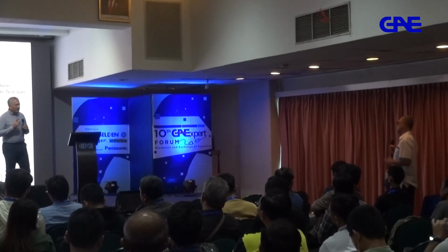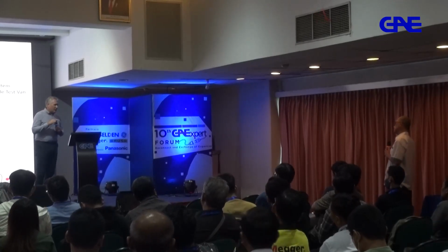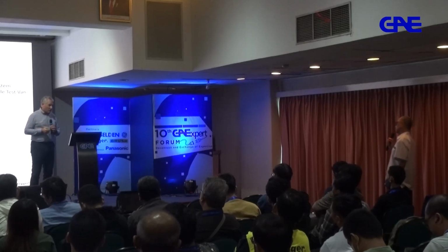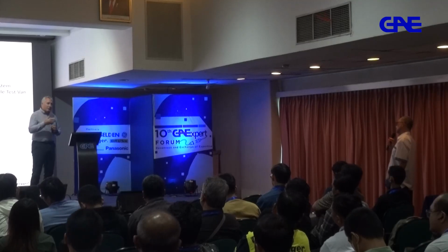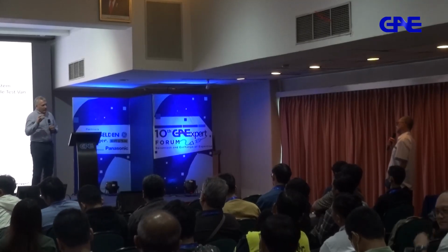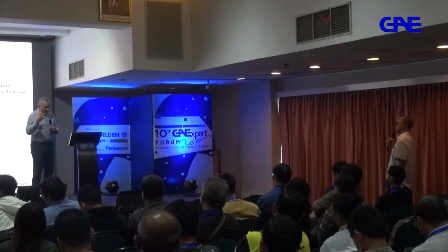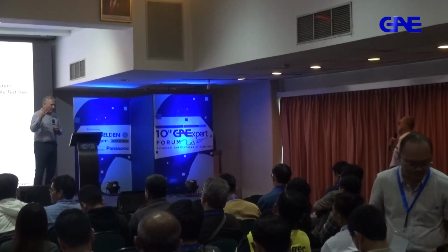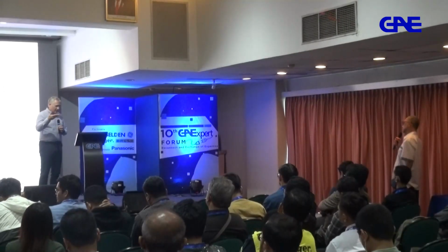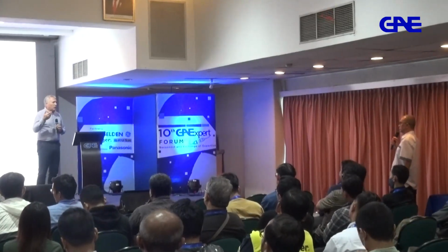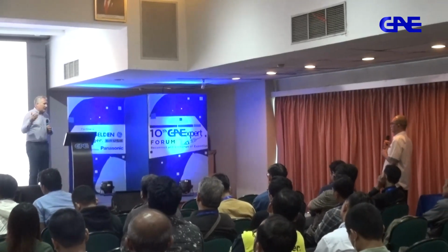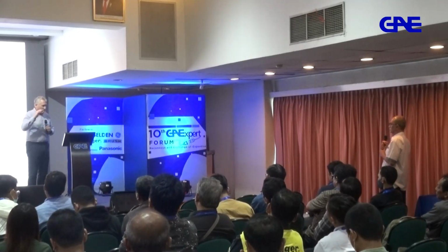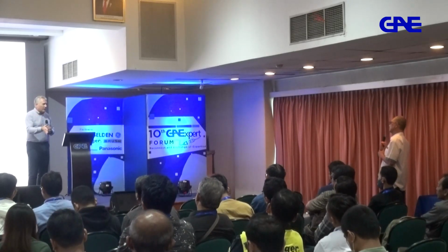Thank you. I understand your concern, but be careful here, because the guidelines that you're going to get are for, let's say, a quiet Faraday cage special test room. When you go in the field, like I mentioned for power transformers, first of all, there are no real numbers there. You have to develop your own sense, because the environment is very important. If that environment is full of corona and so on, when you do partial discharge testing, you're going to see very high values. So you need to use a unit that has a gating capability, and you need to know how to use gating in order to suppress such disturbances and be focused on the asset.